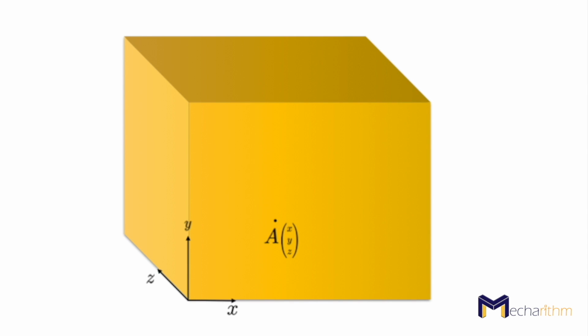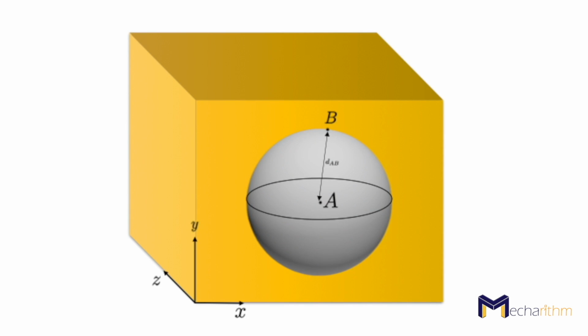You can also imagine this by taking 3 points on the rigid body. For the first point, there are 3 freedoms, X, Y, and Z, and there is no constraints. For the second point, we know that the distance between 2 points on the rigid body should be constant. So B can only be on the surface of a sphere with center at A, and this gives us 2 rotational degrees of freedom. In other words, 3 coordinates for B minus 1 independent constraint is 2 real freedoms.